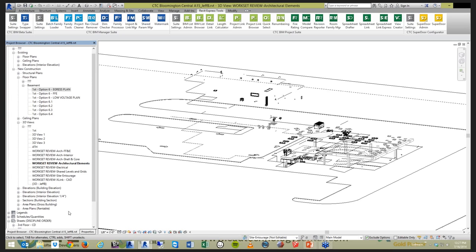We're able to go through and select the views in my project. Oh, it's selecting these because for the view type, I must have grabbed view type contains basement. So it's going through and selecting the views by the property values or name values, so we can pull for name parts, and then we can assign those to the specific project browser organization that we want. All right, so let's go ahead and move on.